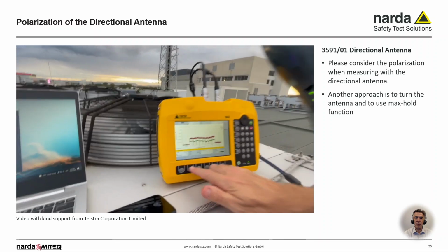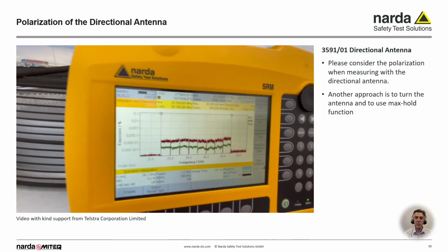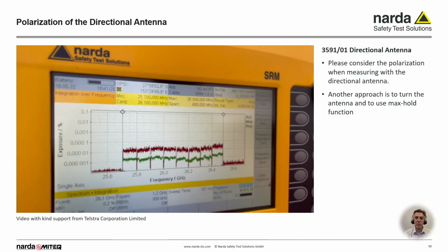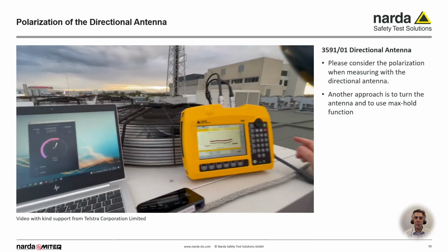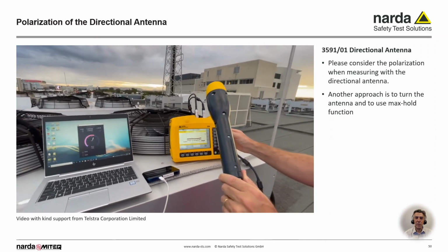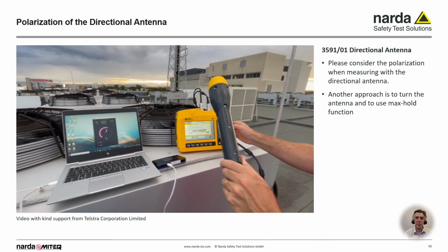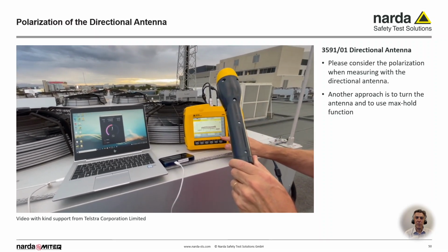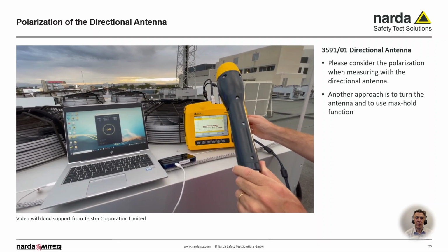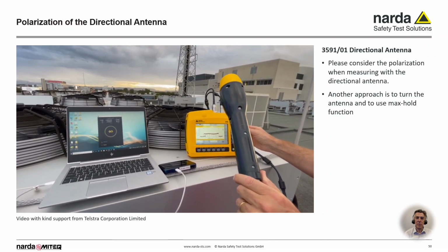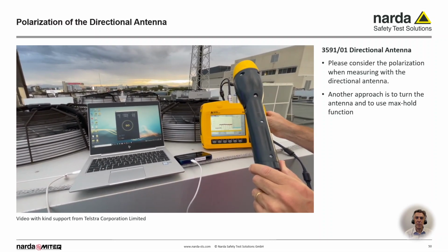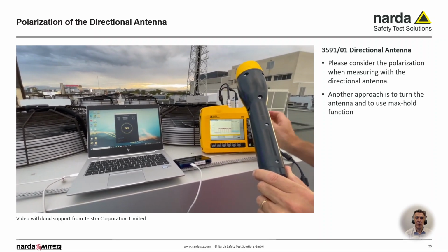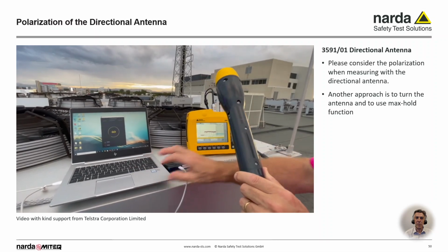I'll go evaluation, integration, and I'm measuring 0.0035. So remember that value, 0.0035. What I'm going to do now is hit save, and that's saved it. Okay, so I'm going to escape out of this, or unhold it, escape, change the measurement range, and then do a reset once I hit my speed test.